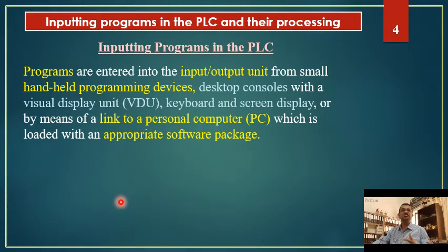So if many such shop floors are available and PLCs are distributed among the shop floors at different locations, then it becomes very essential to have a handheld programming device which could be taken from one PLC to other PLC, and the programmer can think of programming that particular PLC. Otherwise, these PLCs may needed to be disconnected from there and brought to the programming center and program it over there and reattach it to the control room, which may be very tedious job.